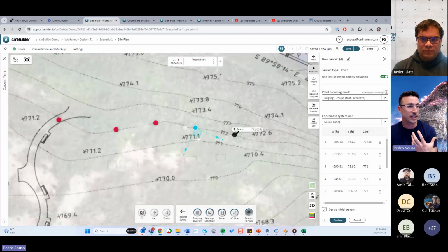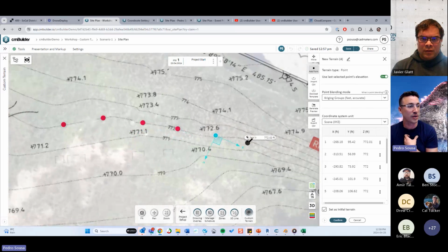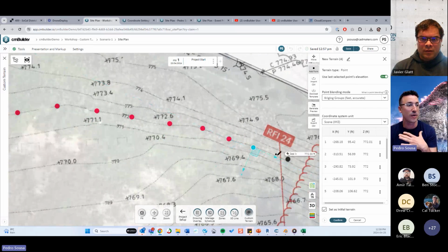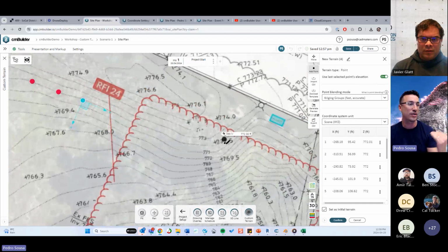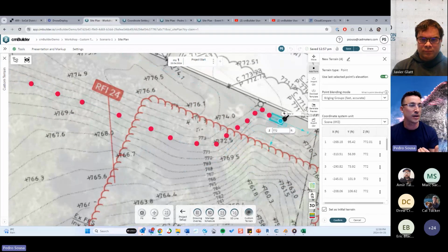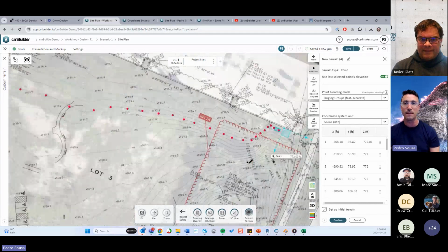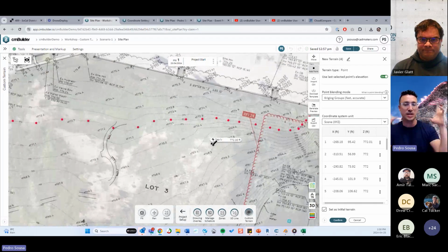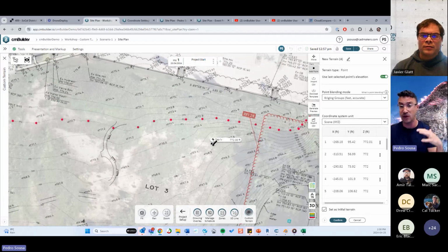Let's say, for example, over here, you want to make sure that this area is correctly covered, or where you have sharp turns of your contour line, like this one over here. So you can just create more points on this area to make sure that you get a better accuracy of that area. But just keep in mind that you don't need to be super precise about this, because there will be some approximations of the shape, right?